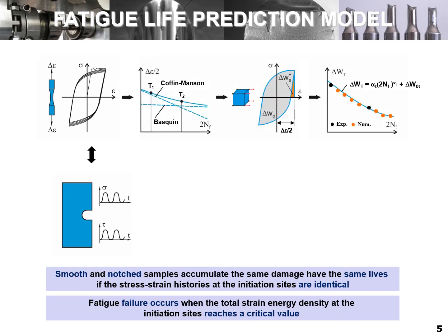The modus operandi consists of 2 main steps. Firstly, we develop a fatigue master curve. In the current formulation, the amount of experimental data is limited to 2 low-cycle fatigue tests performed at 2 strain amplitudes. These tests allow the development of the strain-life relationships and the development of 2 single-element numerical models, representative of the cyclic plastic behavior. By combining the experimental data and the numerical models, we define a fatigue master curve relating the total strain energy density with the number of cycles to failure. Here, the total strain energy density is accounted for by the sum of both the elastic positive and the plastic components.